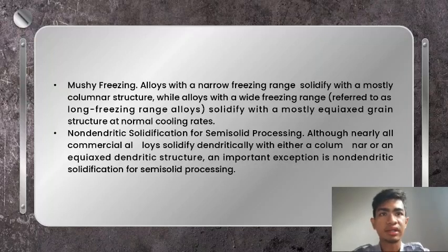Instead, a slurry with an ideal semi-solid structure can be produced directly from the melt if the temperature of the melt is such that many nuclei are generated, and if the nuclei do not grow past a certain point or melt back into the liquid. This controlled nucleation and growth concept is the genesis of various processes and methodologies to generate semi-solid slurries from the liquid state.